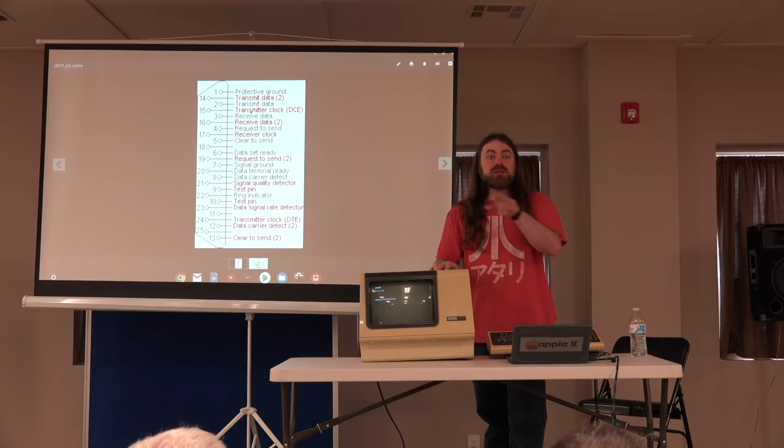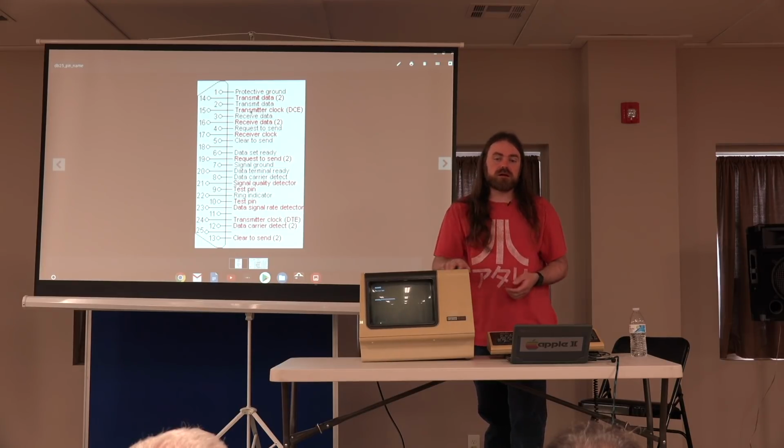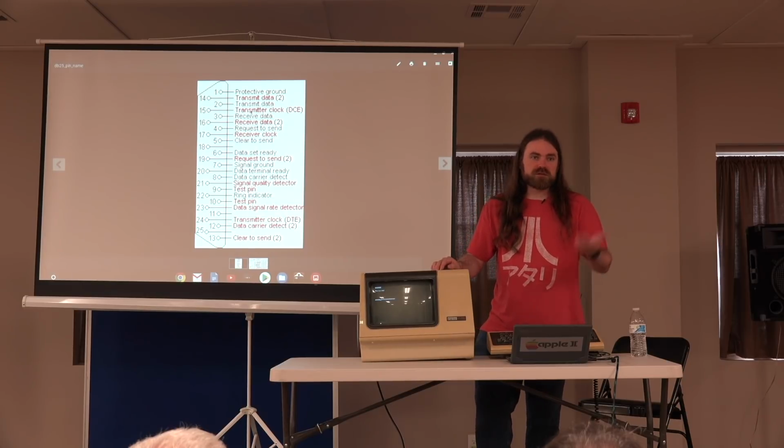No. So if you have a capacitive foam keyboard and you're not sure what's going on, you can take it apart and touch it with your fingers. You can type on it with your fingers because the capacitance of your fingers will work on those pads, but don't short it out with a screwdriver because you could damage the keyboard controller.